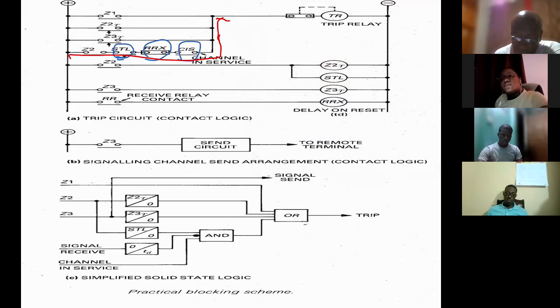And that short delay comes from the zone 2 instantaneous. All right? And this is important. And you know, I have said it quite a few times this evening, and I hope it is now solidified in your minds that our objective is to speed up the operation at the far end. And with that being the case, we have to use the fact that the fault is in that end zone. So we use the zone 2 for our short time lag.